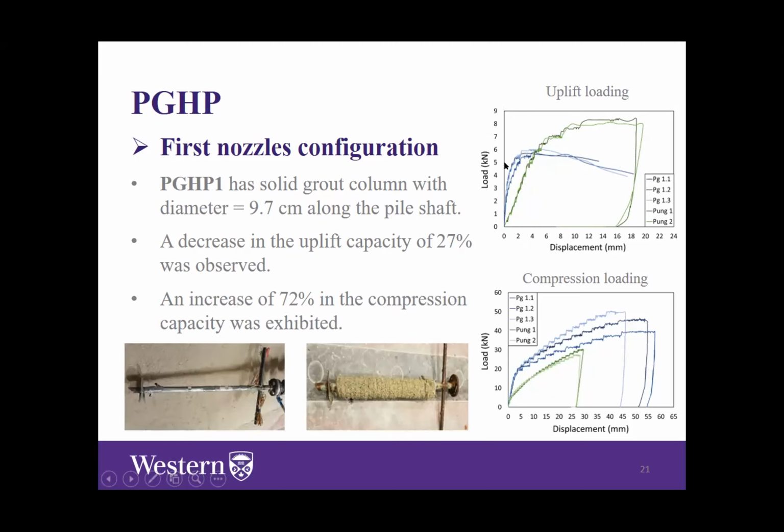However, at design load, the ultimate helical pile capacity is fully mobilized at low displacement level. Its full capacity is normally developed at 2 millimeters, compared to the classical helical pile, which needs up to 8 millimeters to be fully mobilized. This can be explained by the behavior of the pile itself. The classical helical pile still acts as a bearing pile.